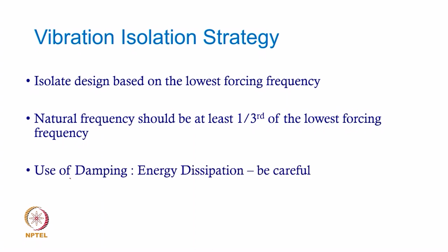Although damping is good because it dissipates the energy, you have to be very careful. We have already seen how damping can be problematic for regions discussed in the plot. Okay. So, do not excessively use damping because it is going to be problematic for most of the frequency ranges. So, it is only good near resonance, and if you take care of resonance, you really do not need damping